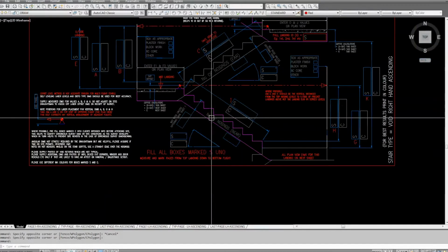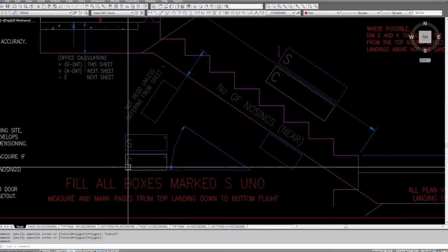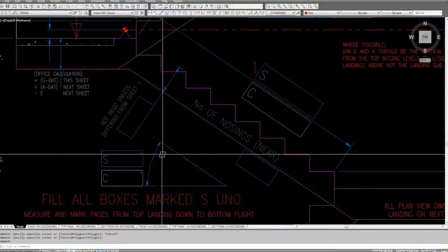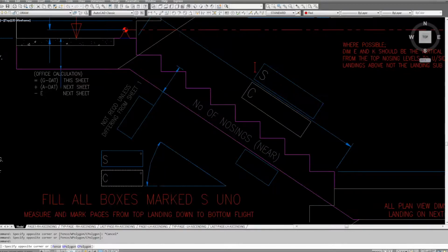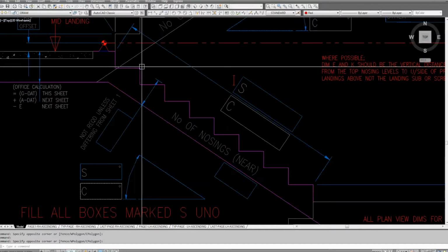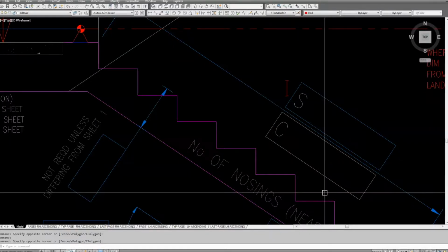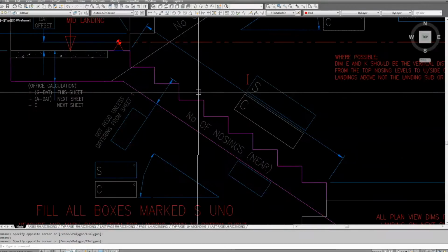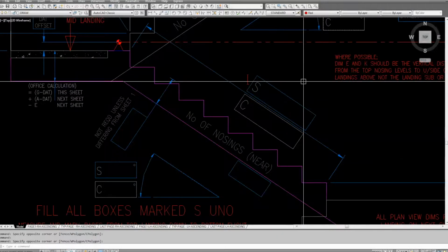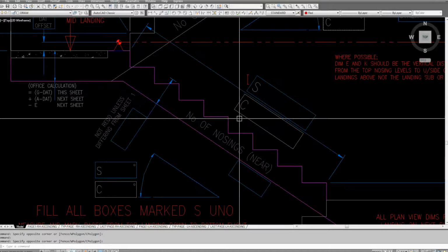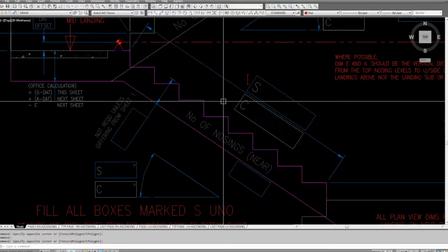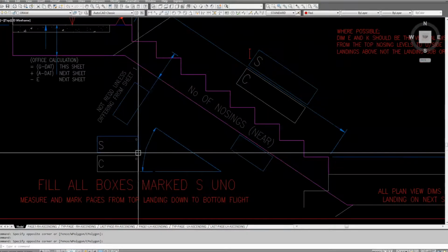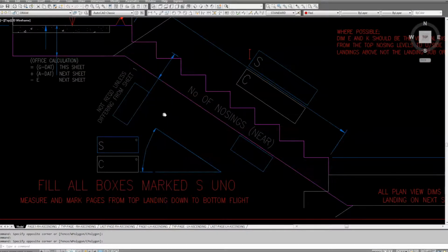So on here you'll notice that I've got an angle for the stair. I don't always measure the angle of the stair, and the reason I say that is if you take a 6 foot level to site and drop it over your nosings and slide it up and down, you'll find that some nosings are high, some nosings are low. I've got a digital angle finder which I drop on top of my level, but it just adds to the site survey process. So if I'm a bit pushed for time, I don't bother with that at all. I just don't take them.